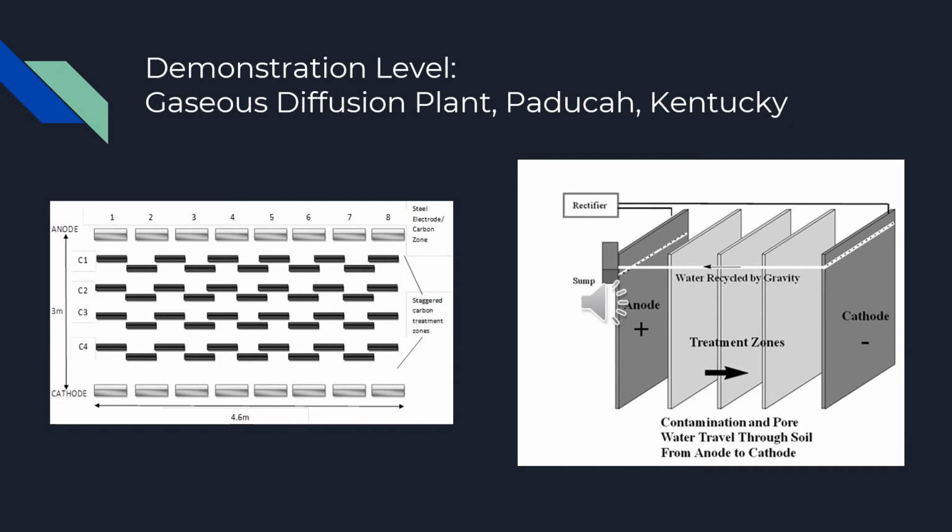Results. The voltage gradient was 0.25 volts per centimeter and it moved the water to a speed of 0.43 centimeters per day. The overall efficiency of the technique was 99.7%. TCE, which existed in free phase in the site, was believed to be removed in the same phase. The emissions were insignificant and the complete cost for this remediation was about $80 per cubic yard for a quarter of an acre at a depth of 45 feet.